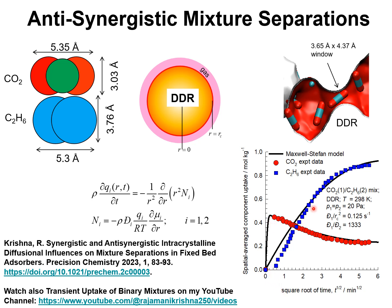To model these experiments, we resort to the Maxwell-Stefan diffusion equations, and the expression to describe the transient uptake of the component loadings is described by this partial differential equation, where Qi is the molar loading of component i at any position r within the crystallite, which is assumed to be spherical, at any time t.